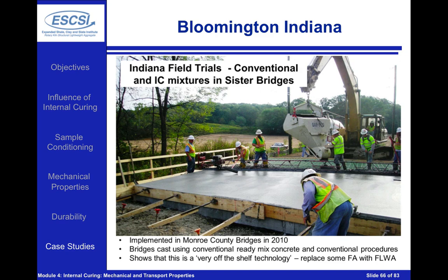They were made using a conventional bridge deck, ready-mix concrete with conventional casting procedures and an internally cured concrete that was really what I would consider off-the-shelf technology. The only thing that was changed in these cases was to replace some of the fine aggregate with the fine lightweight aggregate, and this was a volume to replace the chemical shrinkage water that we've talked about before using the Bentz equation. The only other difference that I would mention in this particular case is that instead of pumping the concrete, it was placed with a bucket. This was done on the first project due to potential pumping concerns.